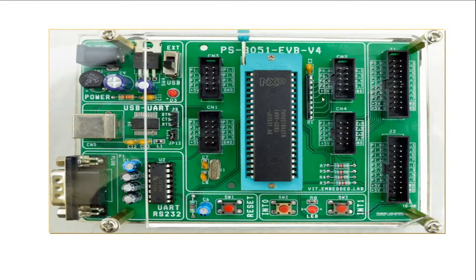For port 0, you have to use a SIP resistor. We also have a 20-pin box header here, which is for external connection. If you want, you could remove this one, because the 10-pin header is enough. While designing the board, removing it would reduce the complexity of the layout.